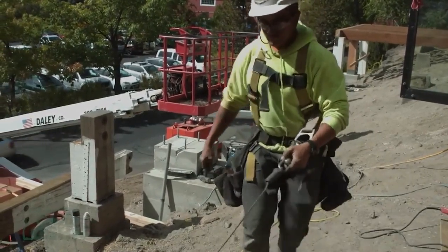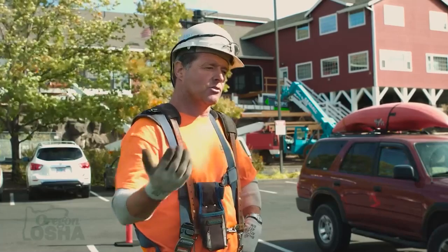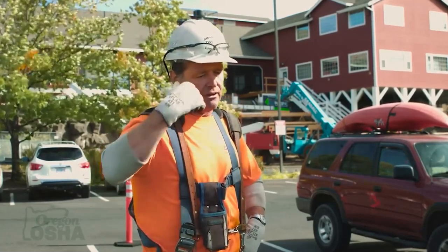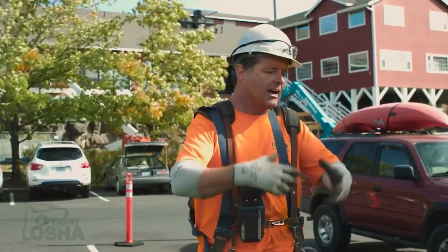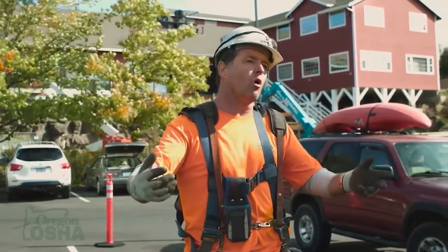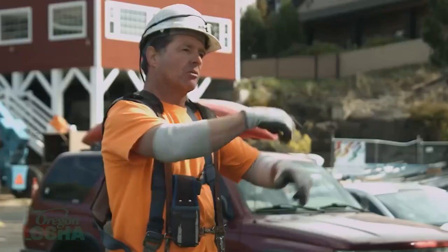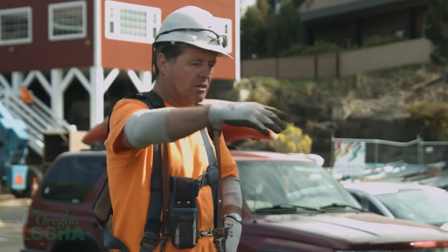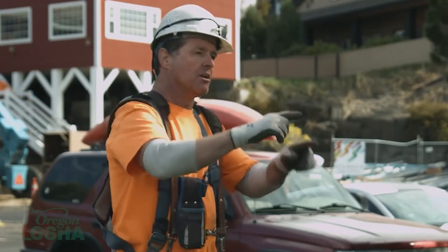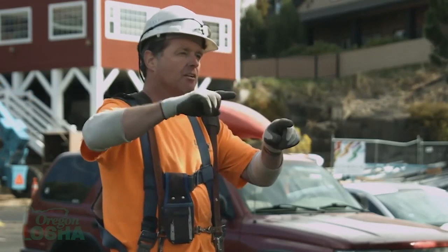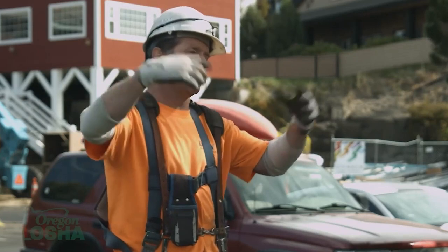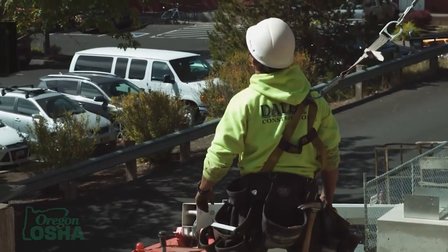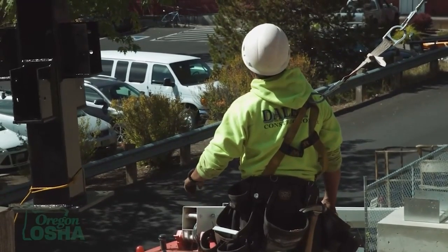Hedge your bet towards safety. There's always a way to be safe, and you can tie off above yourself, and you can roll joist. And the moment you've got a couple of joists rolled or a beam rolled, then you have something you can mount one of those roof mounts to, and then you're able to work a certain radius, and then again you do another one, so that as you keep going, you put another retractable, or you put something so that the person can keep working and not exceed horizontally the vertical drop.